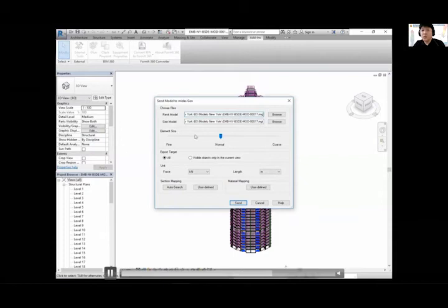So you just choose the name you are going to save it, and here you can choose the element size for slabs and walls that you are exporting. Also, you can choose the unit and just click send, and then it will save the MGT file, which can be imported in Midas Gen. Let's go back to the presentation.